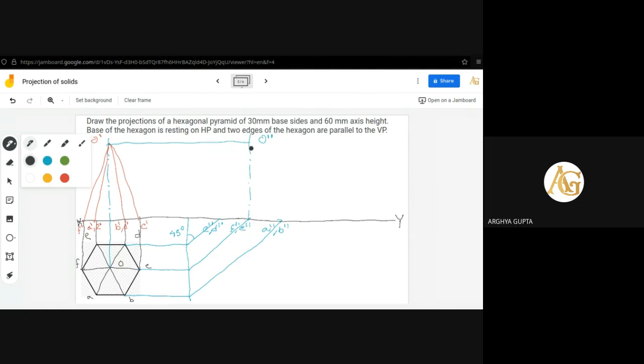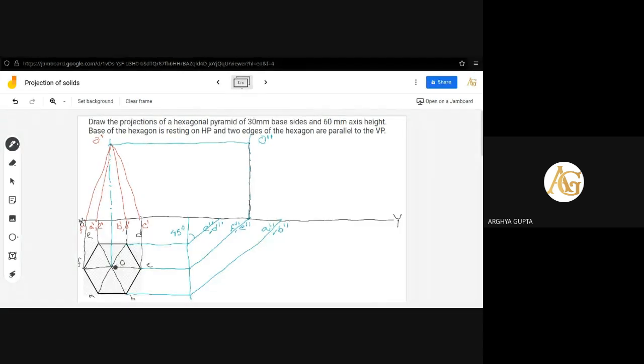So when that continuous edge is coming in front of the axis line, the axis line will not have to be drawn, only a continuous line representing OF, because that line actually represents three lines: the OF, axis, and also OC.